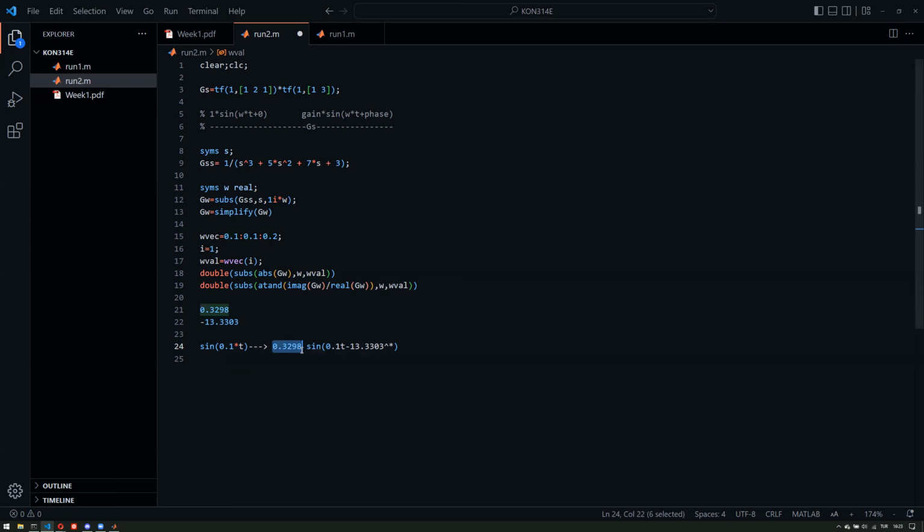One of them is gain, so there will be a gain versus omega plot, and also the phase, so phase versus omega plot. Since they have omega in common, the x-axis can be chosen as omega, and they would be stacked vertically. So you can then match the data from both plots. That's basically what a Bode plot is, and that's also what we are going to do.